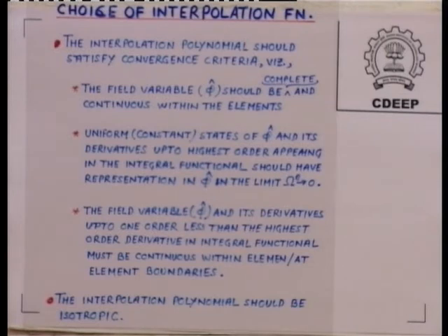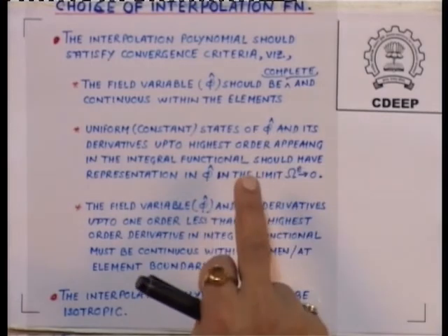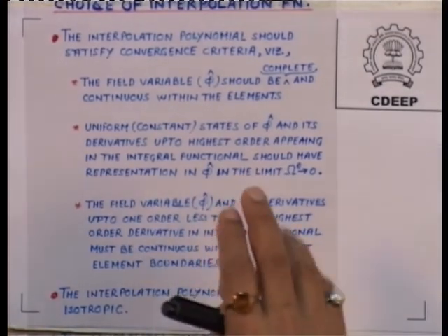No, not necessarily. What I am saying is, not all elements satisfy this, but as the size of the element tends to 0, at least ensure that it is becoming constant. So, even if it is quadratic, as the size reduces, you ensure that it has terms that make it constant within the element. Okay. So, that one, the first derivative should be constant, then it has the requisite property of a proper shape function. Convergence criteria is met.